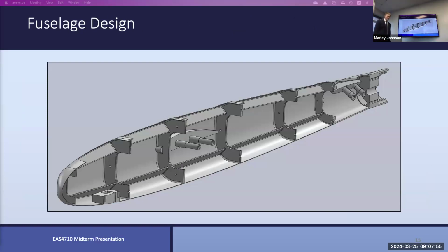Yeah. So I'm looking at your bulkhead attachments, and those holes look to be in the center of acreage. When I say acreage, I mean big, long, open expanses. I'm wondering why those don't wind up closer to the longerons, which would give you a stiffer load path for the loads being carried.